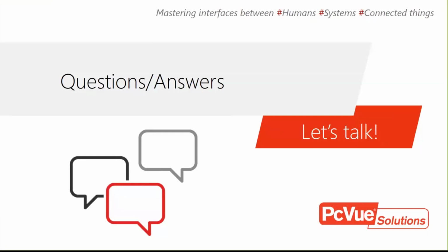So you must put the antenna and move around with your FTD device and check if the signal is okay. This is the situation you need to analyze and control. And if the FTD gives you some good figures about the signal, you can install the gateway and the antenna, and also the device at the right position.